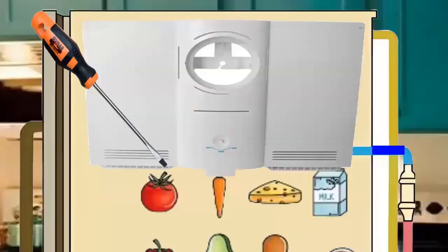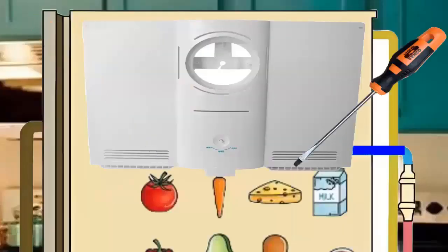B. Lack of thermal exchange. If the evaporator in the upper part is covered in ice, this prevents cold air from circulating downward, causing the lower part of the refrigerator not to cool sufficiently.